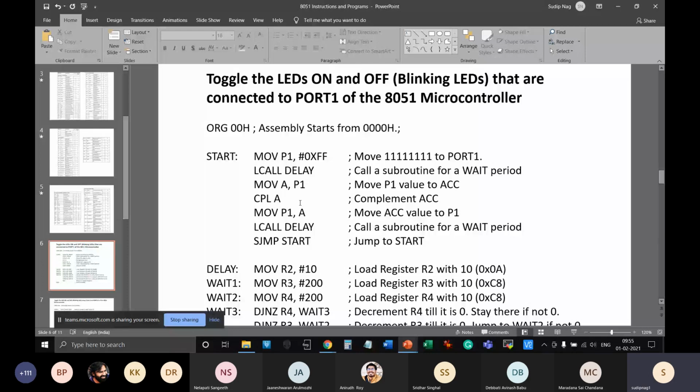So essentially I'm writing everything in this code which will go to the program memory, not to the data memory. If data memory is required, we have to manage that separately, or within the program memory code we have to manage the data memory through our instructions. Assembly level instructions are more efficient than C code, whereas C code is easier to write because it's a high-level language.